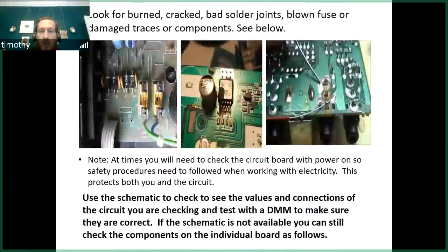That's what's shown here. So here is an example of a bad solder. And so this you would want to catch before you ever applied voltage. But as it gets hot, you can see how this actually burnt the components off. So it will get really hot before this happens. So if you apply power for just a couple of moments and then turn it off, you have a possibility of checking this before it burns out.